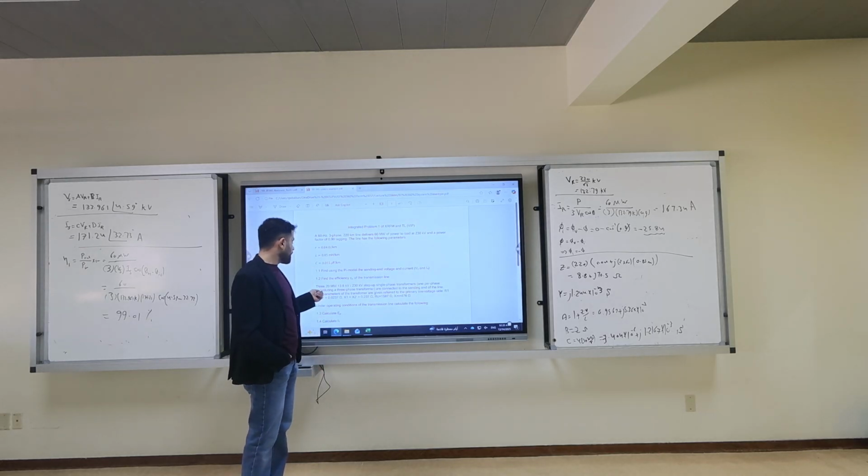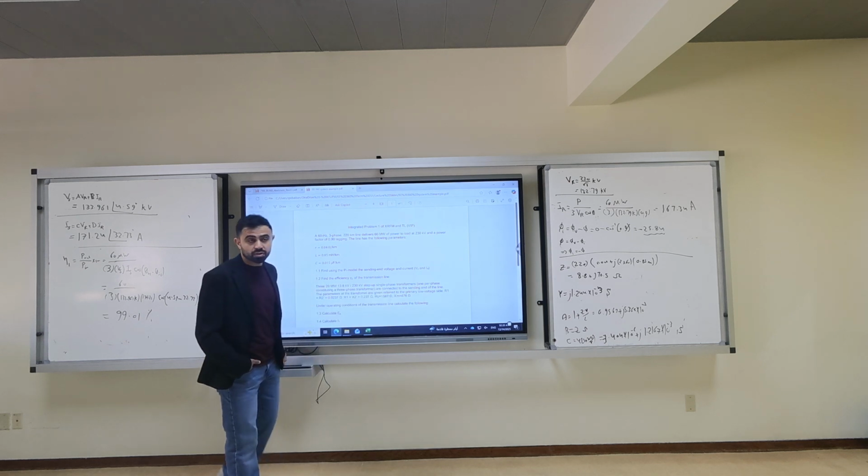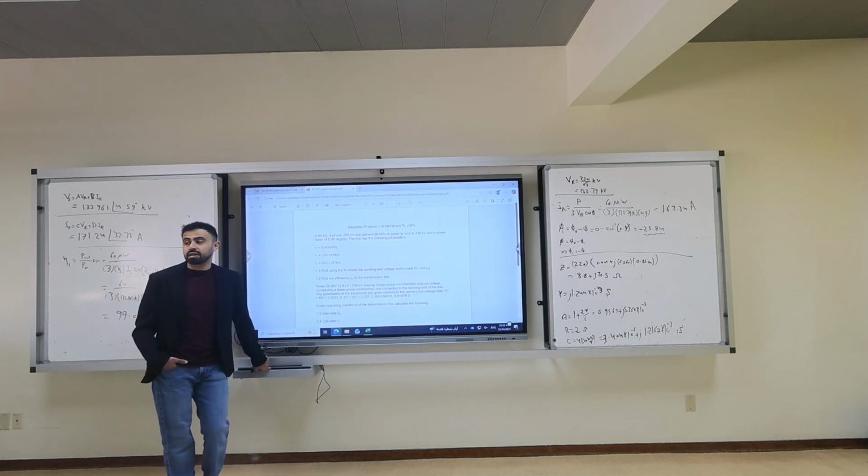The parameters of the transformer are given, referred to primary. We have R1 equal to R2 prime 0.0237. X1 equal to X2 prime is 0.237. R2 is this, Xm is that. So is this circuit 1 or circuit 2? Or circuit 3 transformer? This is circuit 1.